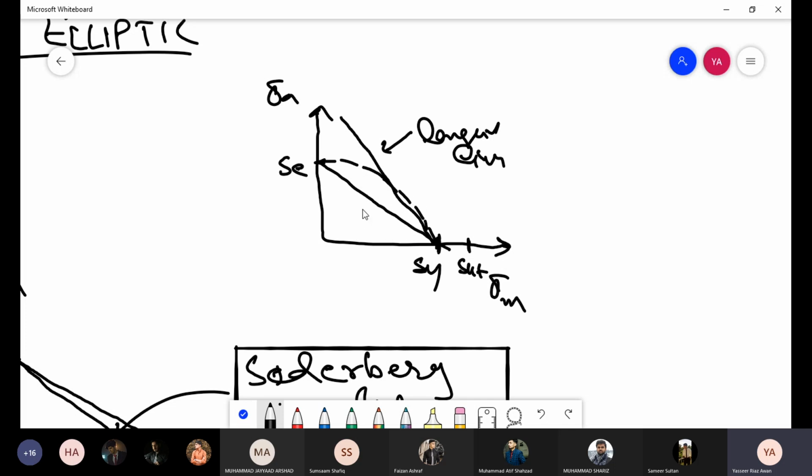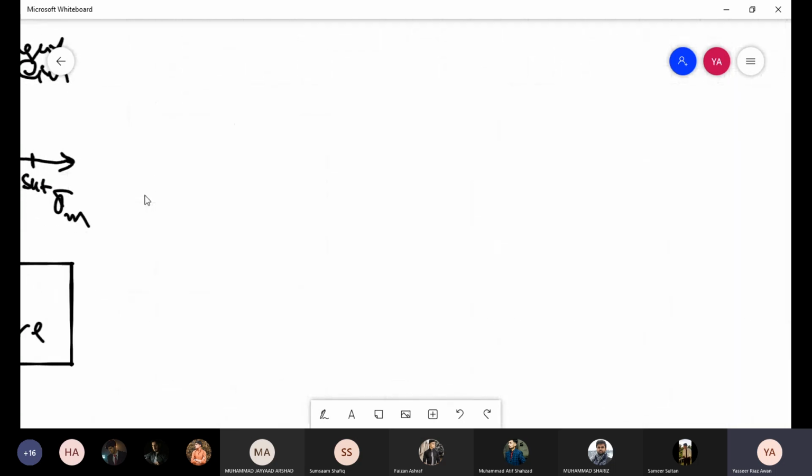So the line becomes very conservative. The ellipse is obviously not conservative in this region at all, but in this region you can say that it is a conservative criterion. So obviously this is all based on experimental data, and these are curves that are fitting through the experimental data. So these are not something that we are deriving from first principles, the way we derived the distortion energy theory, saying that if failure occurs through strain energy, then what should be the equation. This is not something like that.